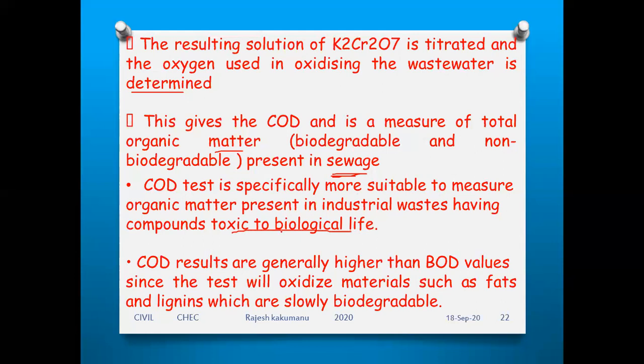Next point. The COD results are generally higher than BOD values. The results you get in the COD are generally higher than the BOD values, since the test will oxidize materials such as fats and lignins, which are slowly biodegradable. The COD analysis gives results that include very slowly biodegradable matter. Since they have a chance of decomposing slowly, the values shown in the chemical oxygen demand are higher than those of the biological oxygen demand.